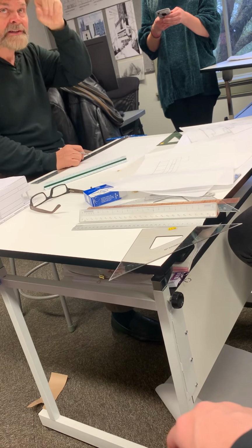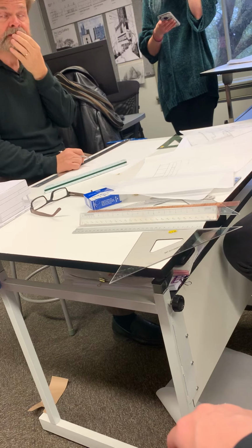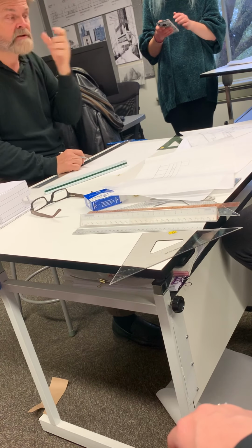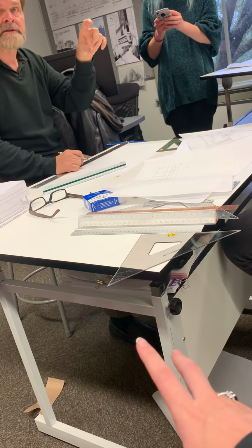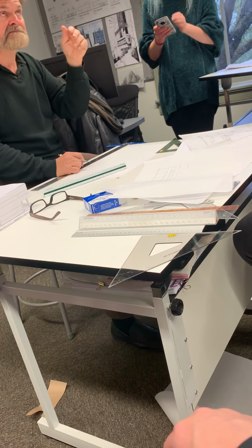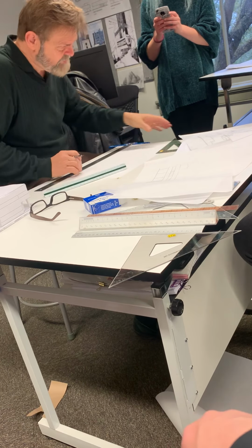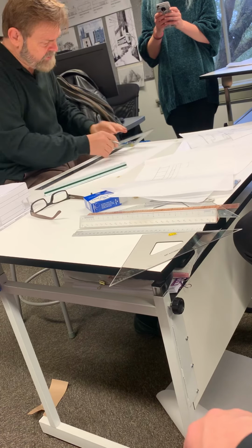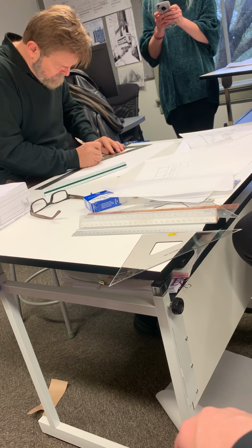So how high is that little parapet wall? I think it's like 3 inches. 3 inches? I think. Okay, it's kind of a little unlikely because you need a cant strip there. But why don't we just agree that it's like 6 inches, okay? That's it. All right, because, and I'll talk to you a little bit about construction because it'd be hard to do it in 3 inches.